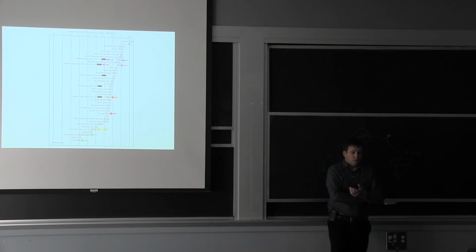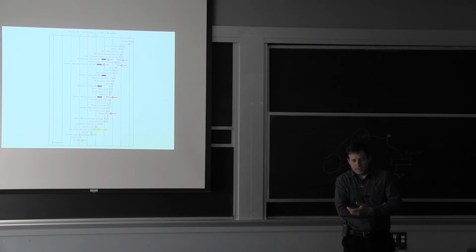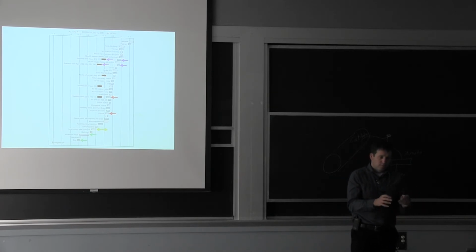One advantage with chrome, and if you remember, we talked a little bit about plastic plumbing, and when you put an organic coating on steel, what you're essentially setting is the clock for how much time it's going to take for the moisture to penetrate all the way to the steel, because moisture and oxygen will penetrate through an organic coating. When you go to a metal like chrome, you almost eliminate that diffusion, but it's still typically not a perfect surface, and that's why you end up still with pitting corrosion.